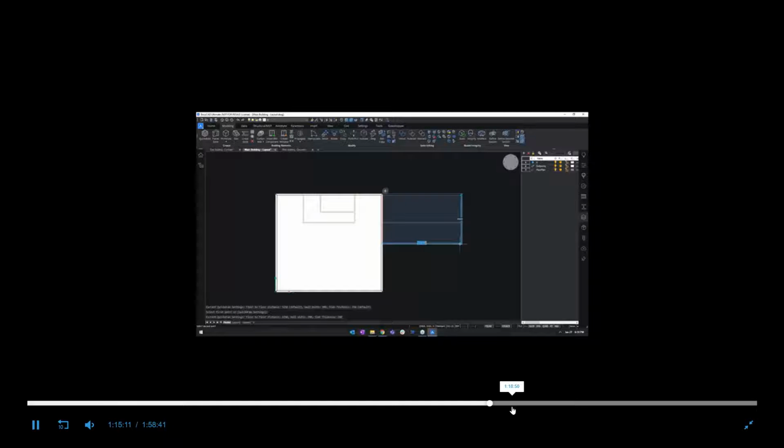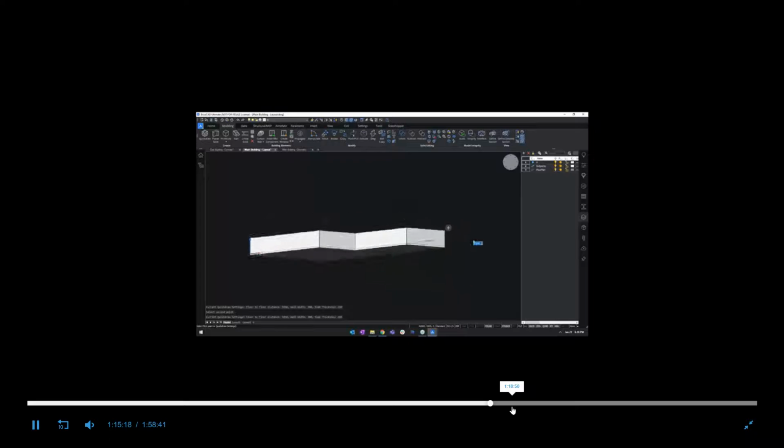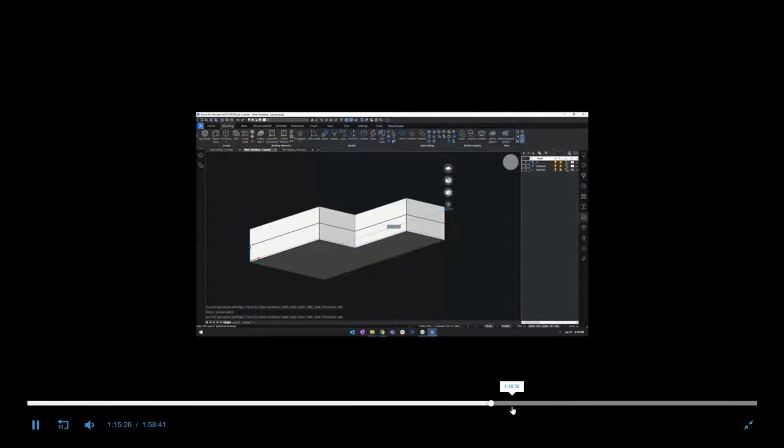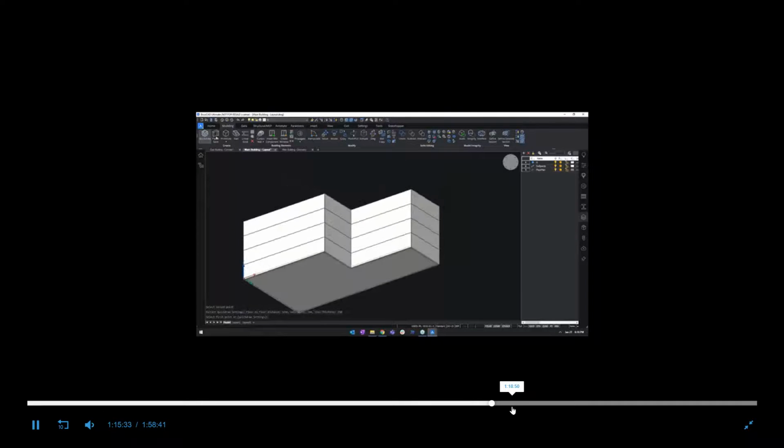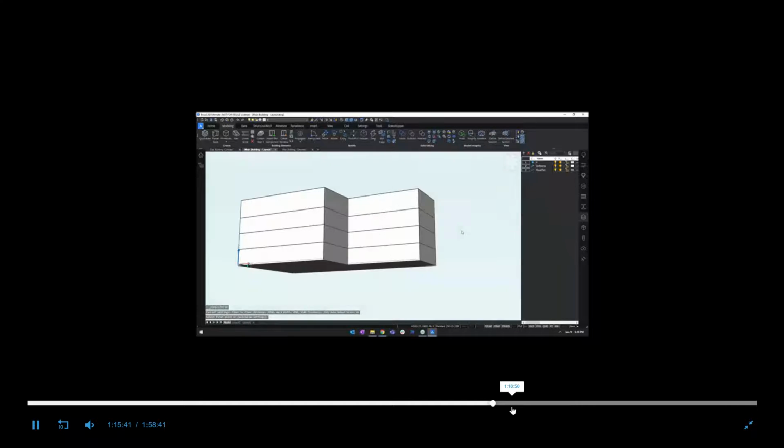But basically, creating walls and slabs based on a 2D layout. And the interesting thing about this quick draw tool is that you can use it in combination with direct modeling tools. I'm just going to create a roof here as well. So even though this is now a very rectilinear layout, I can still use tools like the manipulator to rotate this roof, for instance.